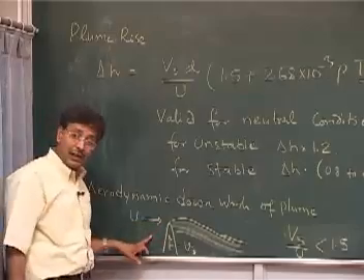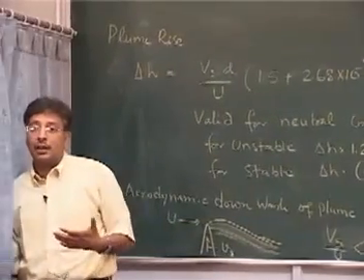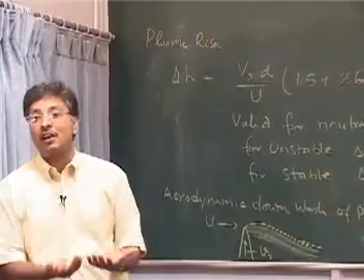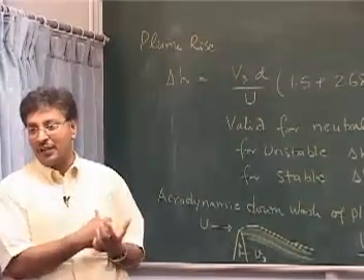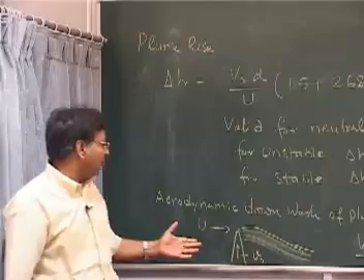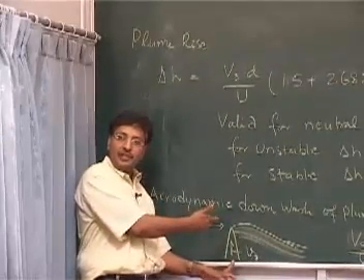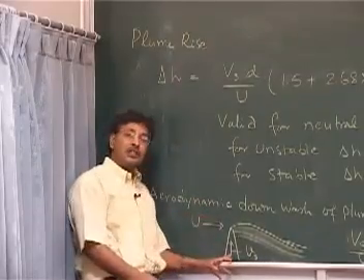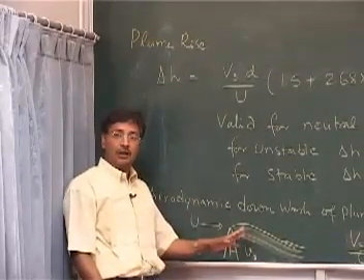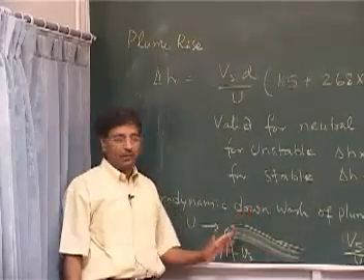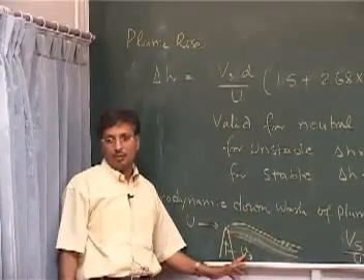Whereas brick kilns, which I gave as an example, are mostly natural draft, with no fan inside. If there is no fan, Vs will always be determined by the temperature difference and similar factors. So these smaller stacks will face aerodynamic downwash because Vs is generally very low.